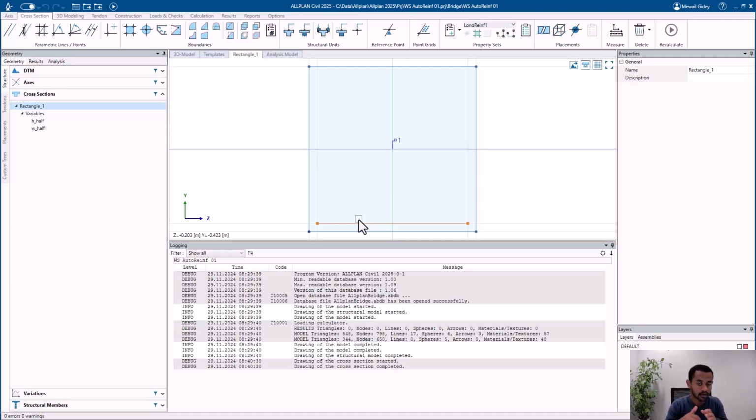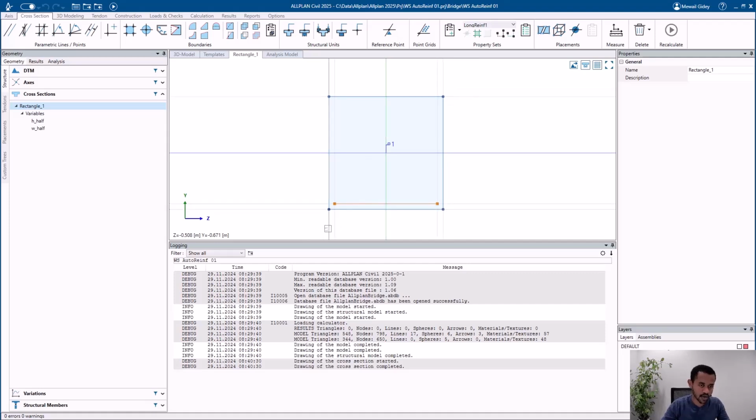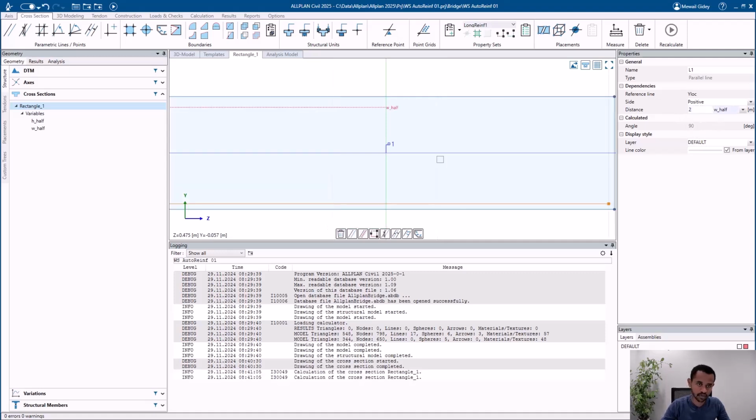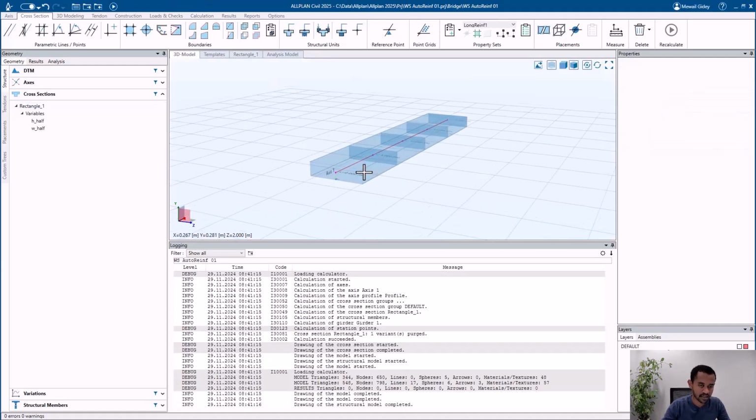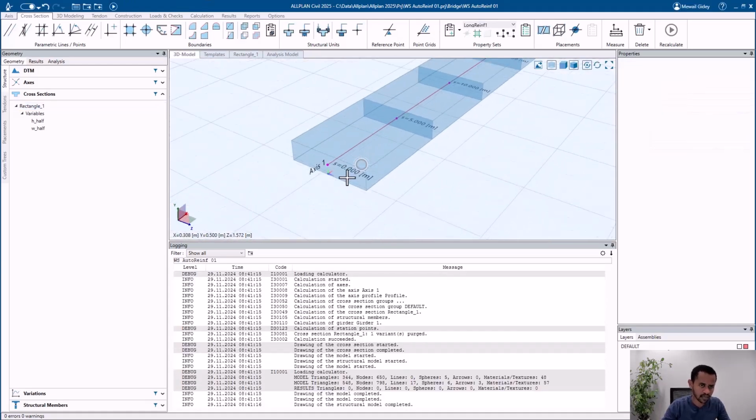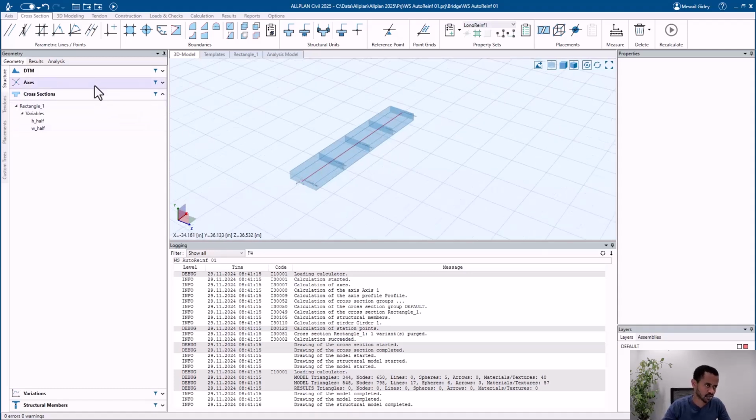But something that normally happens is that we want to change things. So maybe I want to change, for example, the width here. Here it's like 0.5 meter from here. So maybe I want to change it to 2 meters. So it would be something wide, as you can see. Maybe I would also want to change, for example, the thickness. I could also do that. So if I just recalculate now, you can see the structure has changed.